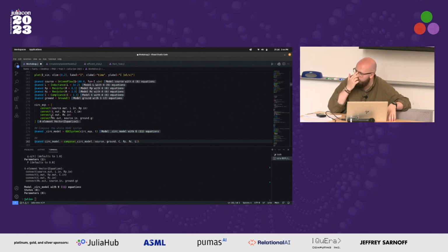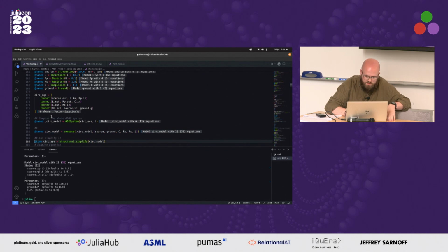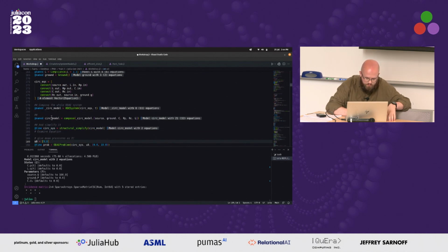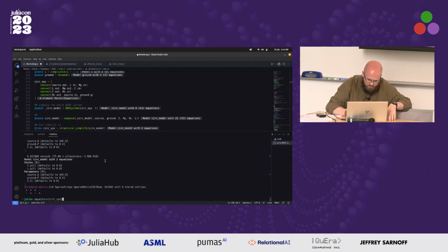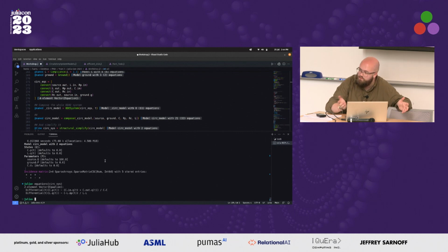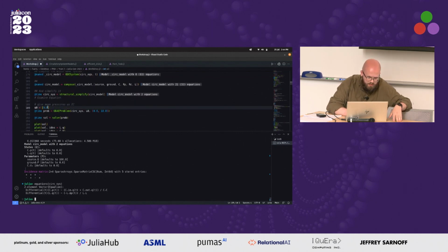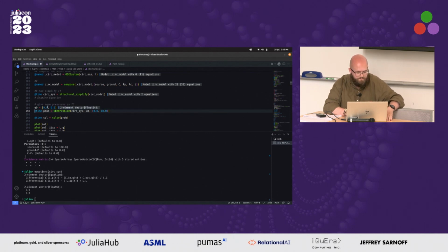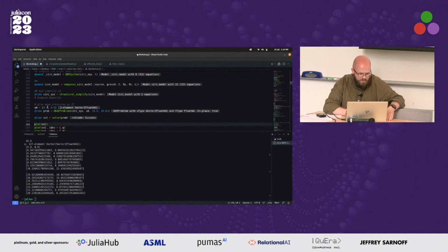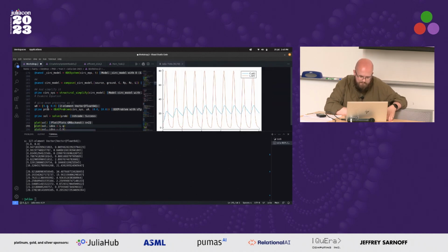Nothing's changed from the series code, no components have changed at all. But this time, we've now got two equations, and we can examine them. So we now need to give two initial conditions. We've got initial pressure, we're going to give just 9, and then an initial flow through that inductance, say 0. And we can solve that problem there.